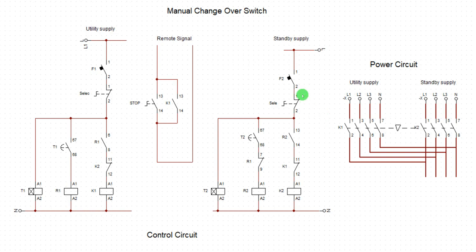Another one, I decided to use MCB for the control instead of fuse. But if you are able to get a good fuse, better. Otherwise, use MCB so that it can be reset. Whenever it's bad, you can reset it back. Because if the fuse blows and you go there for troubleshooting, you might not be able to see the fuse to replace. So I prefer MCB.